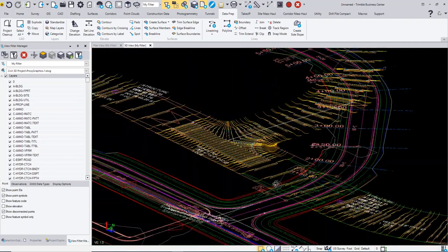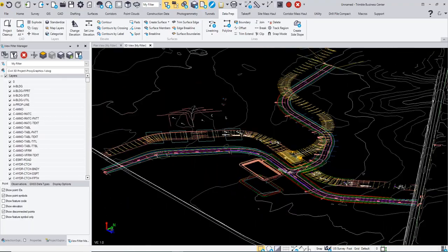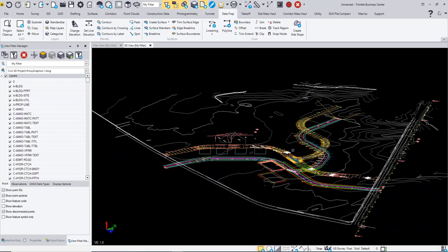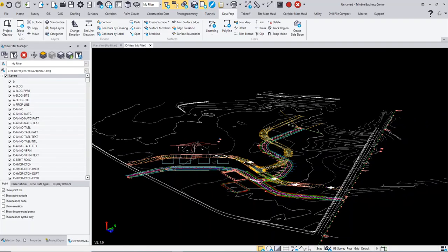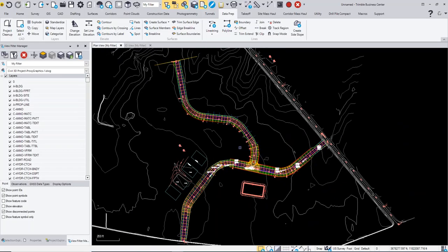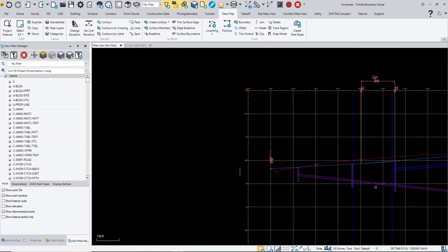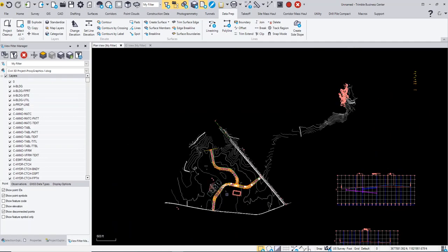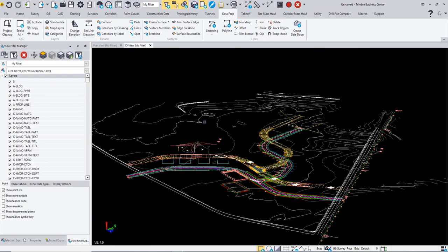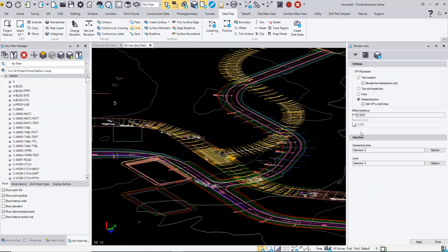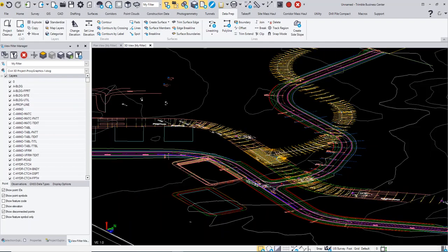You can see, again, the sample lines that are shown there are all 2D. The contours are 3D, and then any 3D polyline is 3D as well. So that's the results of Proxy Graphics 1. So just by setting Proxy Graphics 1, I get all this information that I can use. I can elevate these lines here fairly quickly using the elevate line command that lets me use the intersection lines, where I can select the cross sections and then select all the lines and elevate them accordingly.